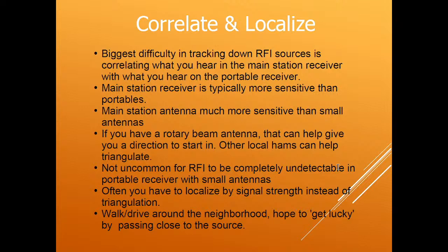Even if it's just a dipole, it's going to give you excellent sensitivity. Or if you have a rotary beam, that's going to give you a lot of signal into a very sensitive receiver. So what this means is that fairly small signal levels of RFI are going to be annoying. They could be S7 and be annoying if you're trying to have a QSO.